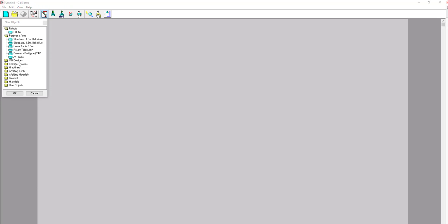The third option here is the input-output devices. RoboCell input-output devices can be connected to any free input-output terminal. The robot controller has 8 digital inputs, the one I showed you before. You connect your input-output devices to the controller, and you will be able to use them.